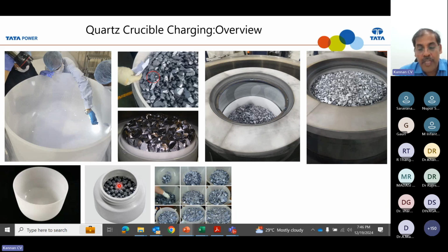So we need either a p-type substrate or an n-type substrate to create the p-n junction or np junction. The raw material, pure polysilicon, is an insulator. When you grow it in a rod shape, very high purity, it is still an insulator, so we have to convert this polysilicon into a conducting nature by doping with either a p-type based dopant or an n-type based dopant.